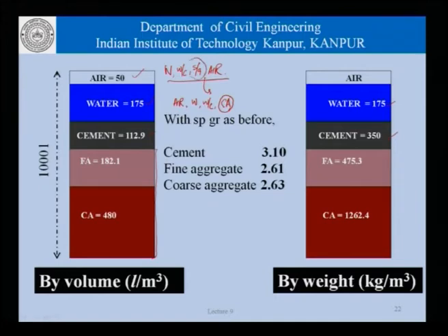In the S by A route, we said that well, we will apportion this in a manner that the sand content, which is this part, is a part or a fraction of the total inert material or the total aggregate content, the coarse aggregate and the fine aggregate. In this approach now, we are saying that no, that is not what we want to do. We are fixing this content to be 52% and we are fixing this to be 48%.